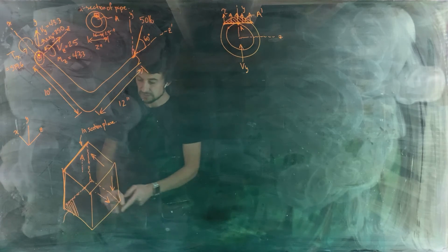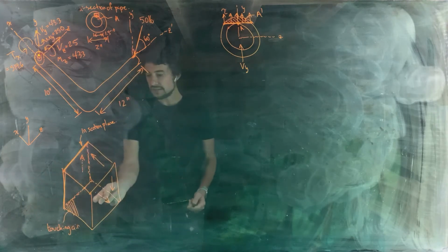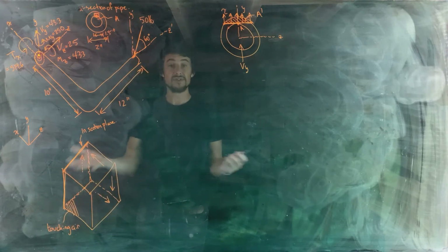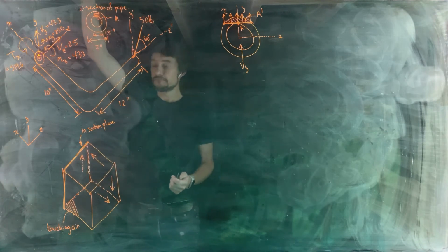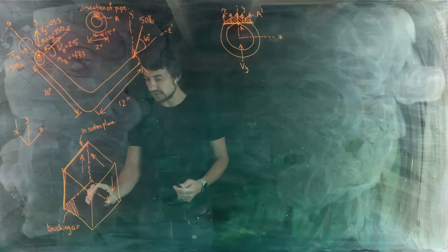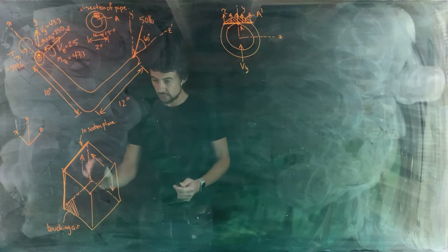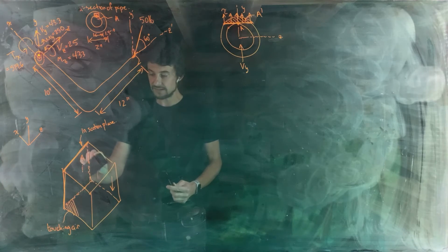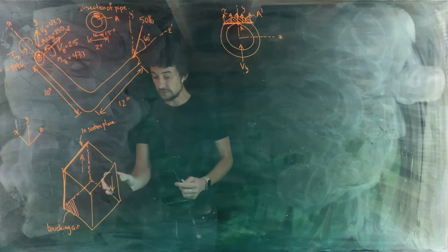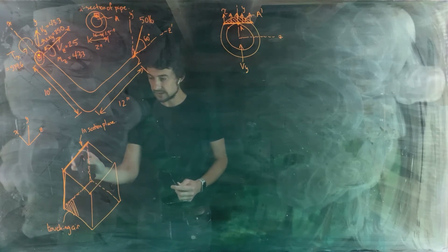Because that bottom face of the element is touching air, there is nothing to actually support that shear stress. The shear stress can't exist. It can't be applied to that face because there's nothing to apply it. If the face is touching air, it has to be stress-free, which means for static equilibrium to exist, this stress can't exist. And if that complementary pair of stresses can't exist, neither can the original set of stresses.